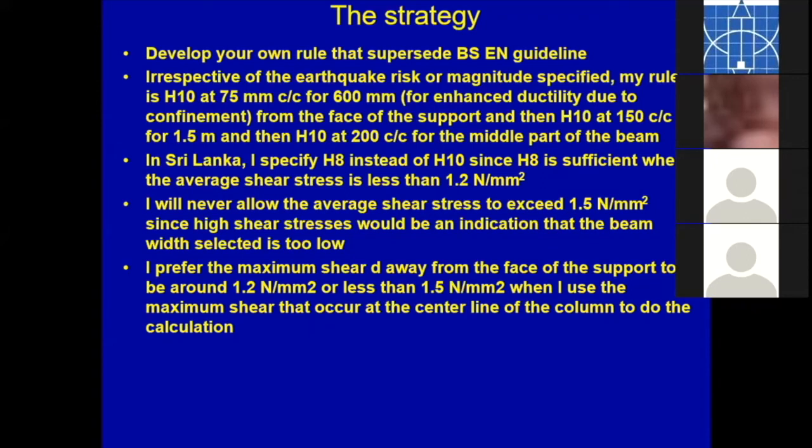The extra cost will be only about 2 to 4%, 2% of the overall cost, or 4% of the structural cost. So basically, it's not too much money, it's only a little bit of money extra to make the building totally safe in case of earthquakes. So it's not difficult. You must know it's another rule of thumb. Another rule is, if you adopt earthquake detailing,